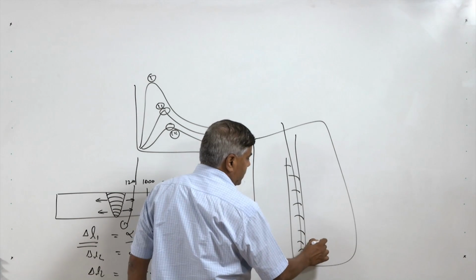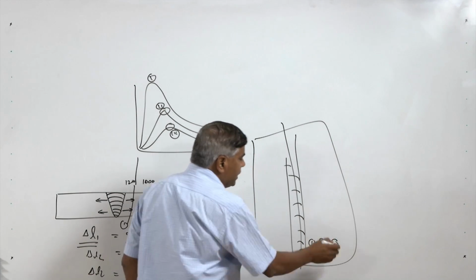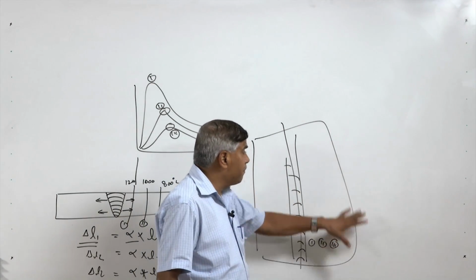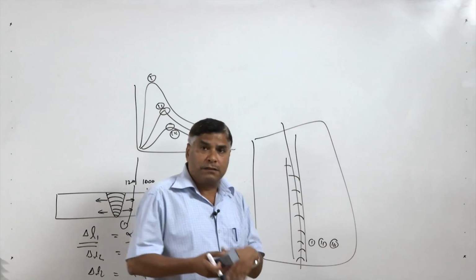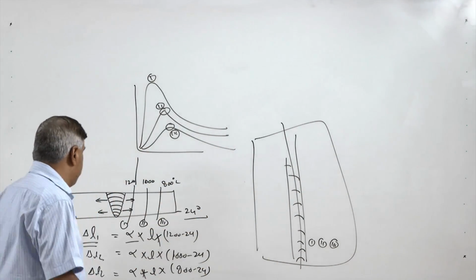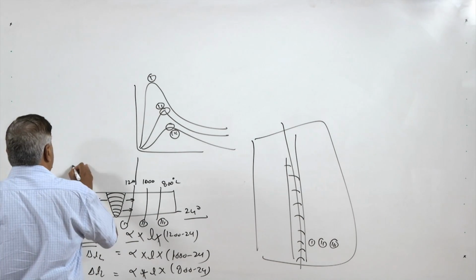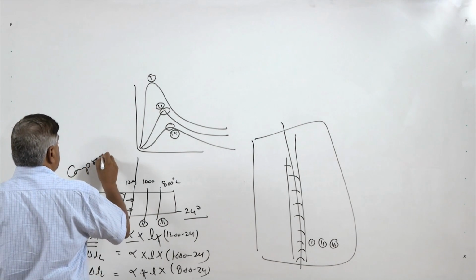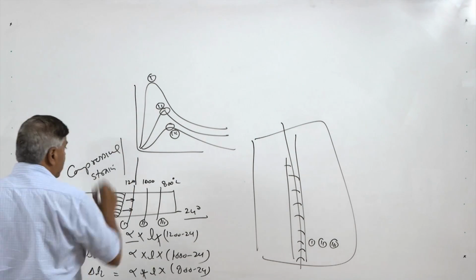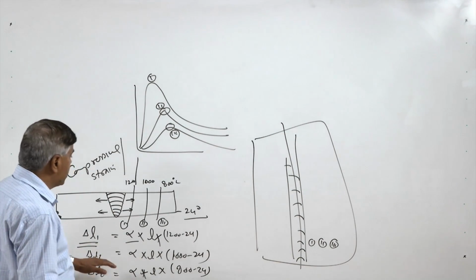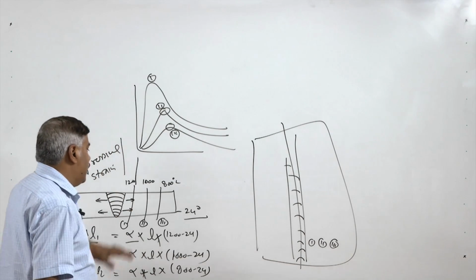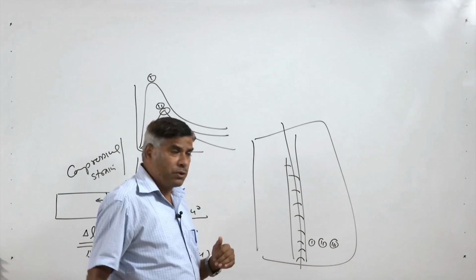Like one area, second area, third area, all these zones are being heated to different temperatures. But since these are an integral part of the entire plate, their expansion will be restricted, so they will feel compressive strain during the heating because their expansion has been restricted. And once things have been cooled, they should shrink, but that shrinkage is also restricted.